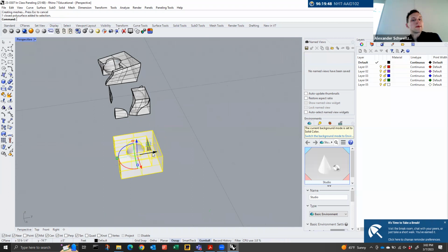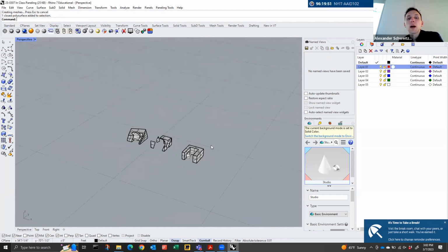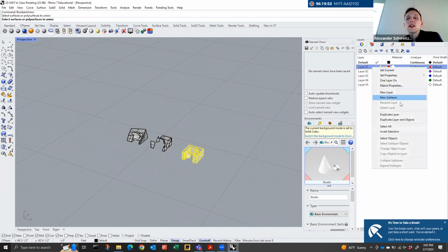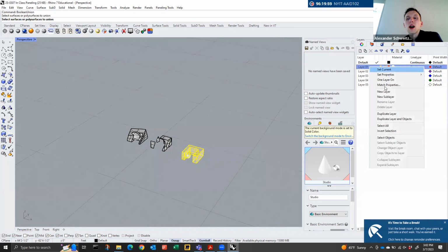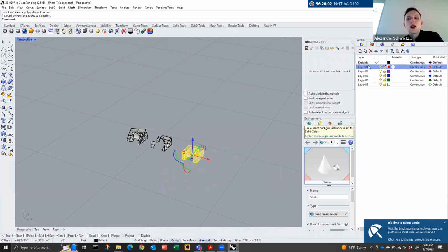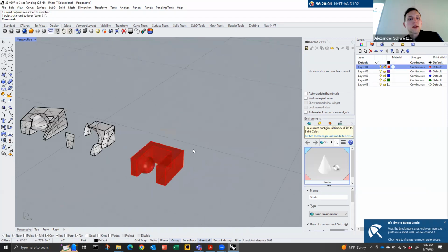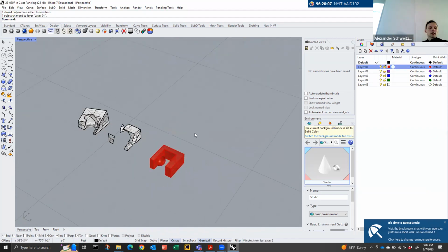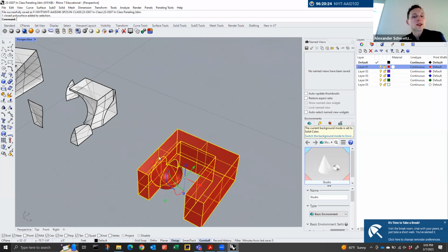All right, great. So here's my tile. I'll make it a new color layer. The way that this works is that there's 2 things it needs to know. It needs to know a surface to reference, and it needs to know a point grid system. A point grid system is the individual objects that are basically the corners to which it will panel and put multiple pieces onto.